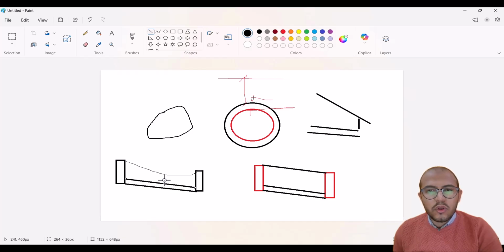So if you are considering the cover along the line and have the terrain model activated, the program SewerGEMS will consider 1.2 at this point and put the pipe with the minimum cover here. So the cover will be more than 1.2 here and more than 1.2 here also. I think it's clear.